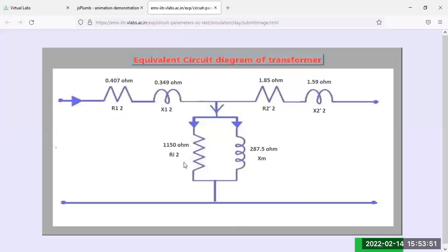So you maybe calculate the value of core loss resistance. That means 230 divided by, first you calculate the value of cos phi 0. So cos phi 0 is equal to how much? That means power divided by V1 IE, no load current. That means 50 divided by 230 into 0.9. So the zeros are cancelled from numerator and denominator. And now 5 divided by 9 into 3, 27, and 9 into 2, 18, or 20.7. So 5 divided by 20.7 is your cos phi 0.